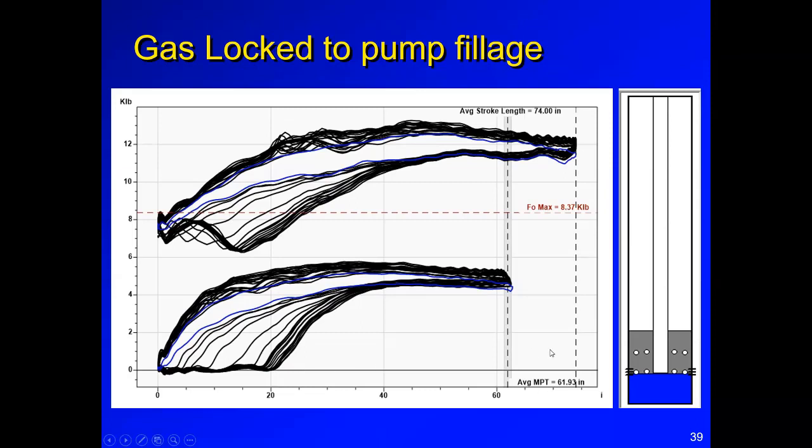Well, because you have slippage inside the chamber. Even if the standing valve is not opening to bring fluid from the well, there is fluid falling around the plunger, and that's what we call slippage. Even a new pump will have that. So you have fluid falling through the pump clearance between plunger and barrel, and that's filling the chamber.